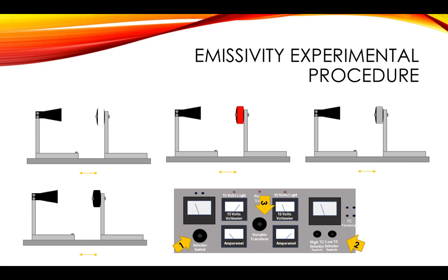When the temperature and millivolt readings were constant, these were recorded in triplicate, and it was taken into consideration that for the matte black plate, an emissivity equal to 0.95 was presumed in order to calculate the other plates' emissivity.